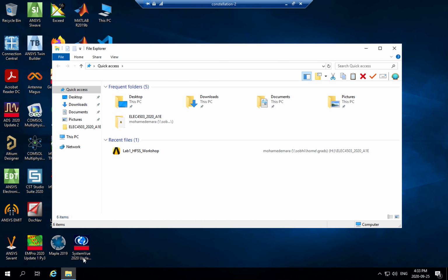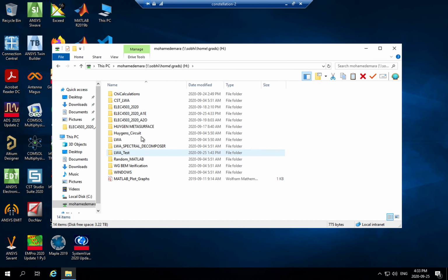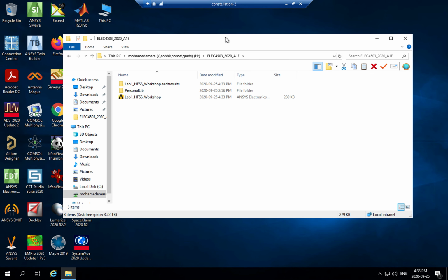And one other thing I wanted to tell you is about the results. If you go on to the folder where you have the project, there are two important files. There's the project file, so that is the project, and this has everything you need to produce your results. So if you're running through problems and I tell you to send me your HFSS design, all I need is that file. It's an AEDT file, called ANSYS Electronics Desktop file, and it's a fairly small file.